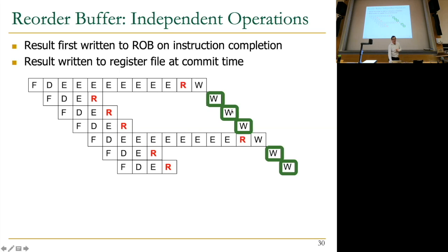So we're updating the register file in program order, register file and memory. But we're going to look at the register file most. So then the question is, there are some values in the reorder buffer that are produced by these instructions. If there's a dependent instruction, how does it get that value? Ideally, we would like to supply that value to the dependent instruction because these values are already produced, so that we can make progress. That's the idea. We're going to see that.